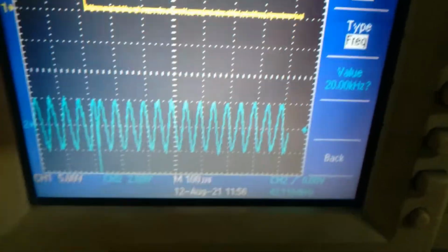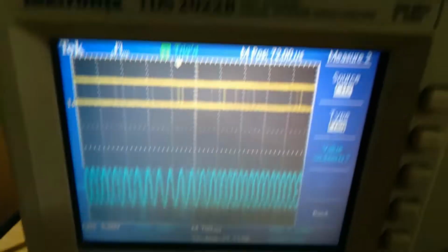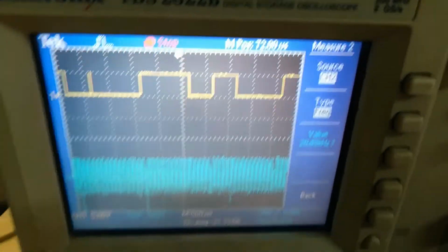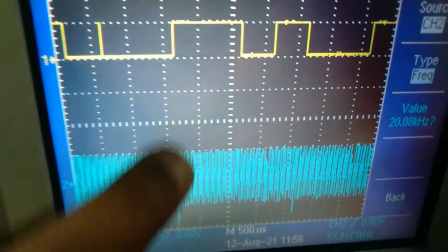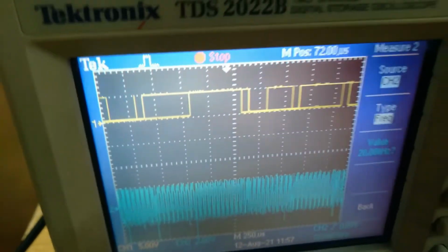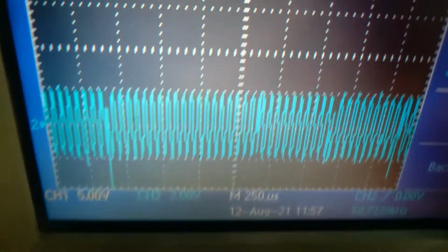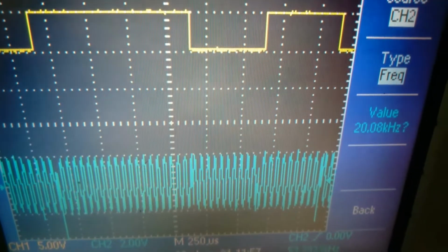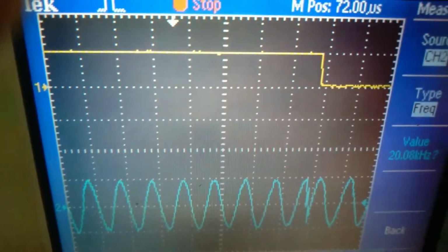Once again, I'll put it in the run mode, and I'll show you the multiple phase shifts which are being created. You can see that there is a break in the waveform for every transition, right? If I expand this, you can see the phase shift which has been created. So at every transition there is a phase shift in the PSK output. It's a 180-degree phase shift, which you can observe, right?